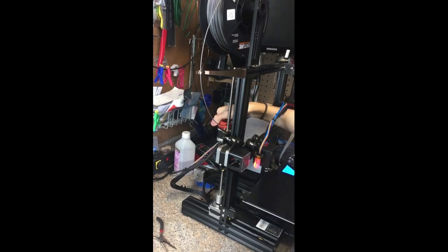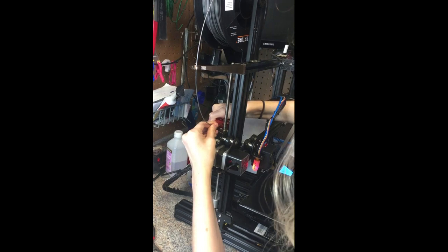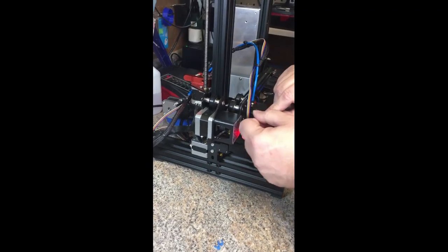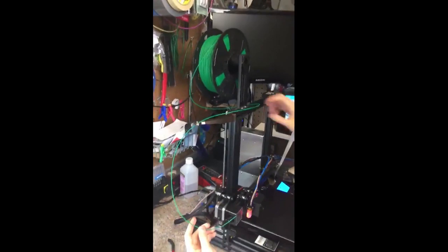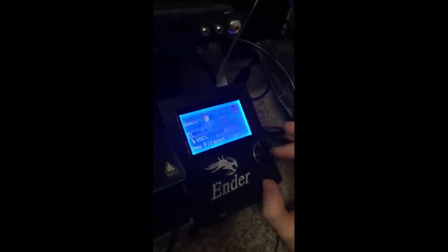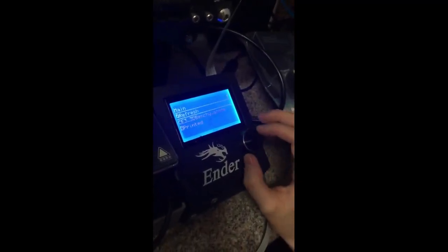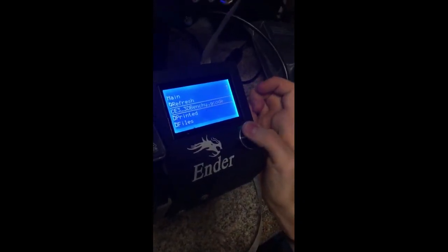To switch out filaments, apply tension to the back part of the extruder and pull the filament through. Sometimes the filament can get stuck in the tubing and will need to be unscrewed to pull out. When putting filament back into the printer, make sure the plastic stays on the track and feed the filament through until the old color comes out of the nozzle. Finally, you can go over to the menu screen, click Print from SD, refresh, and find your G-code file. Your printer will preheat, then automatically begin printing.